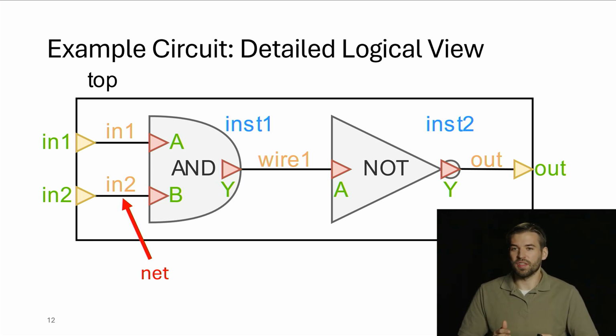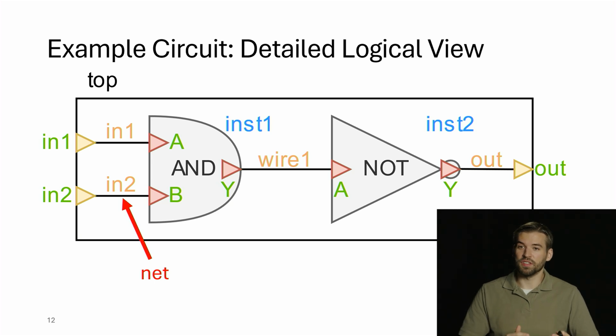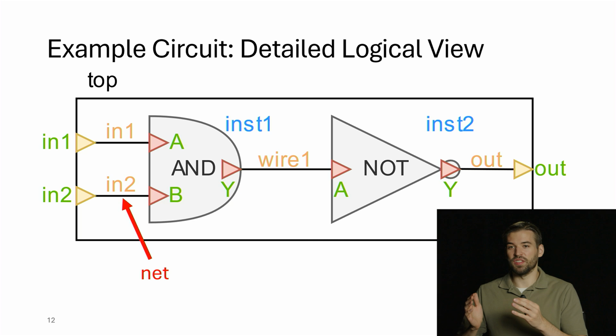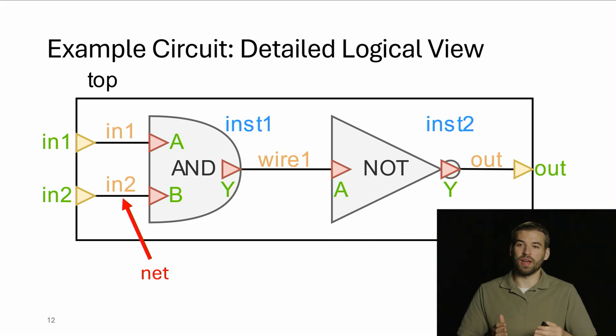You may notice that there's actually a little bit of a difference between here and Verilog because we have both these terminals and then we also have nets, which are a separate entity. In the physical world, we usually like to keep them named the same so that it avoids this sort of ambiguity. But do note that they are actually separate concepts, separate entities. We just call them the same to keep them from being confused with each other.